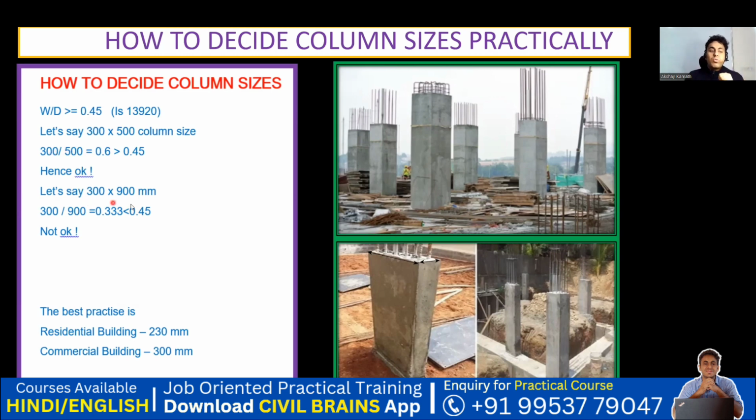Now let us say I'll take one more dimension, which is 300 by 900. Now again, 300 divided by 900, if I do, I'm getting 0.33. But 0.33 is less than 0.45. Agree with me? So that means I cannot go with this column. I mean, when I say I cannot go, this dimension is not a good dimension according to our Indian standard 13920 code book.